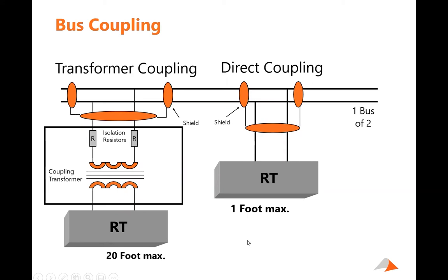There are some weird things that do happen. There are people who have implemented, I've seen 70 and 80 foot stubs, and that was very interesting. You definitely want to be very, very careful when you violate the spec on the rest of the bus. That bus, if you tied anything in on any of the couplers, it would die. You could have one coupler for that LRU and one for the bus controller, and that was it.